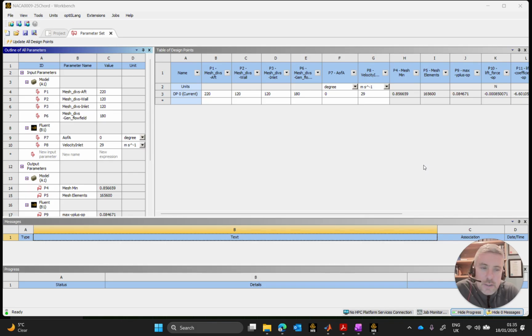I didn't do that. So when I went back in to make a change to a parameter, an AOA that I had instead of an A of A for angle of attack, although it was deleted out of Fluent, it kept showing up in my parameter table here. So what I had to do was export this project and import it into a new project. When I did that, it cleared it, but I had to redo Fluent again with all the messing that I had done on it to try to clear the AOA. So there'll be a couple of slight changes in it from what you had seen before, but other than that, everything is identical.